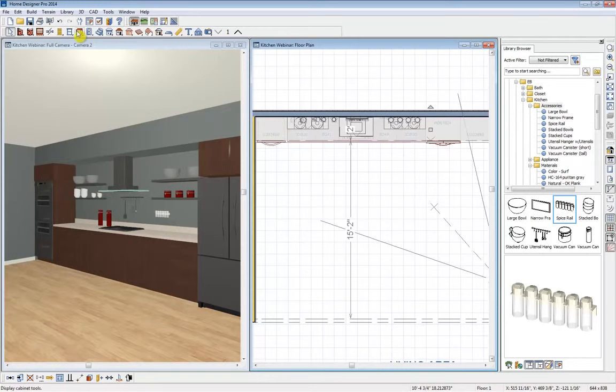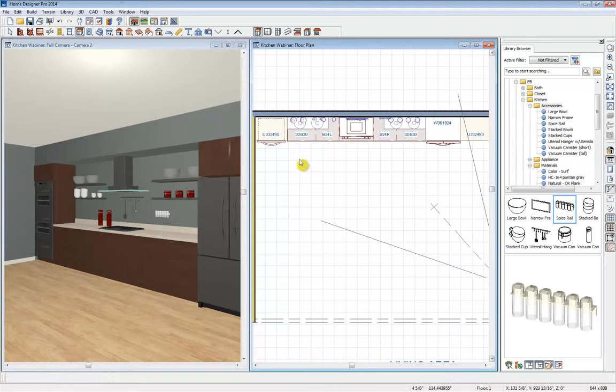So we can go up to our cabinet tool and the base cabinet, and this will enable us to be more specific. So just hold down Shift on your keyboard and marquee around those items. And we'll see down in our very left-hand corner, the very bottom, 5 objects are currently selected. So that's good to know. We have 5 cabinets there.